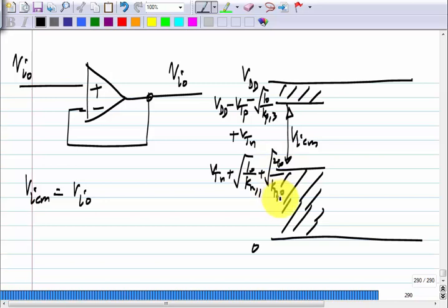Okay. So, first of all, when you design an op amp circuit, you design a circuit like this, you have to choose Vi0 somewhere here, isn't it? Obviously, otherwise it will not even work. Is this correct? So, we assume that output will follow the input. All this is true when all the transistors have high gain and everything is in saturation and so on. So, first you have to choose the value of Vi0, you have to look at the input common mode limit. Okay.